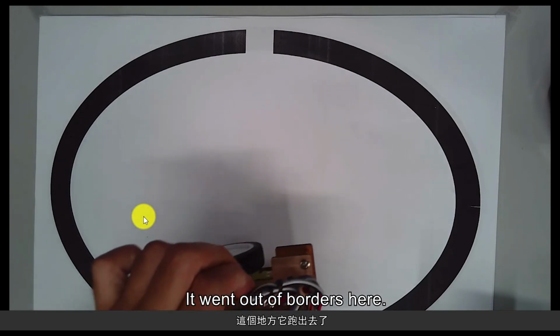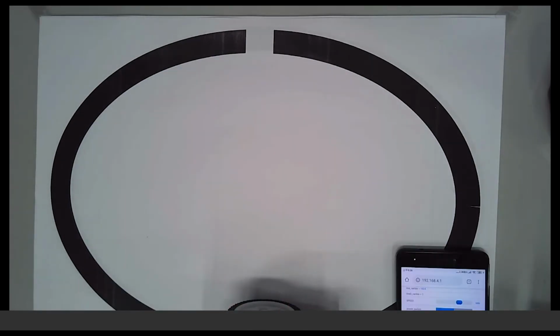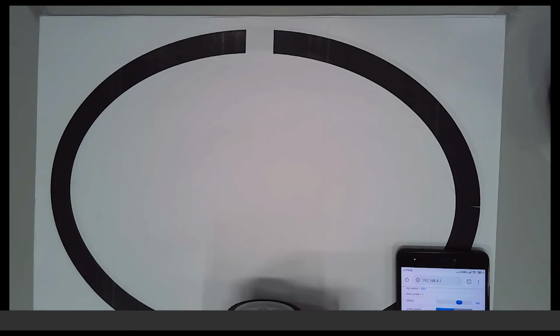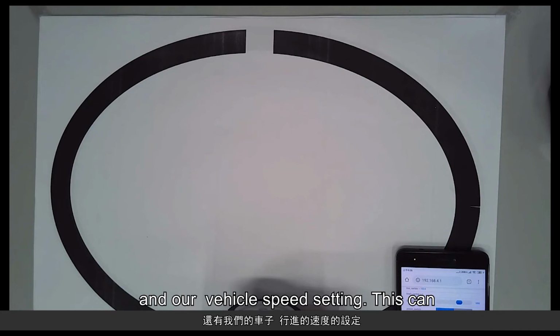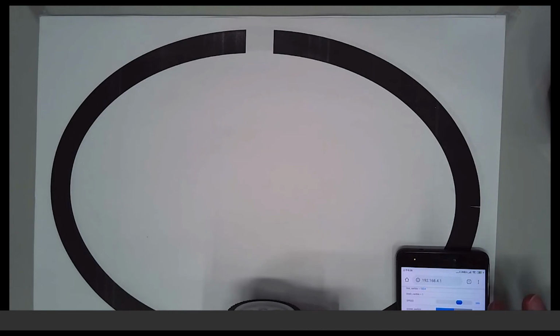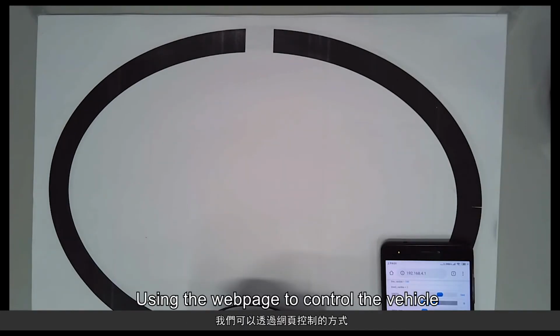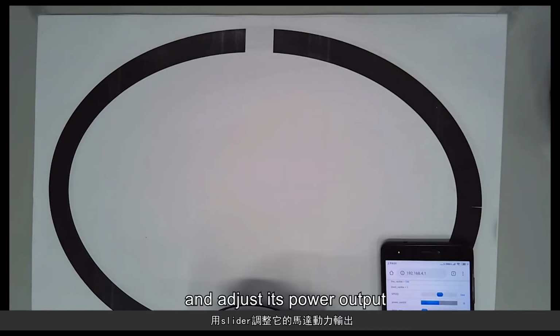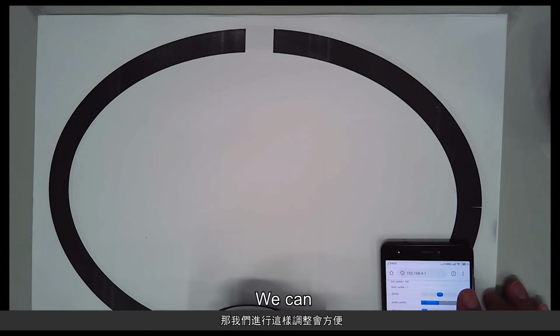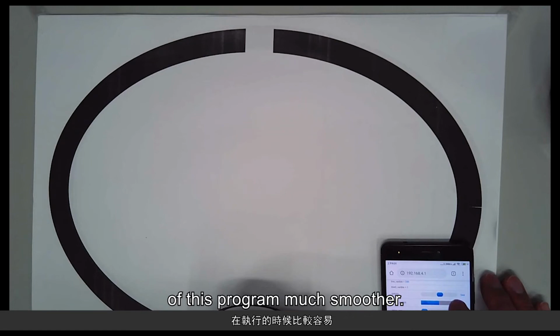It went out of borders here. When a vehicle tends to get out of bounds, we need to consider our delay time and our vehicle speed setting. This can be easily adjusted from our web page. Using the web page to control the vehicle and adjust its power output, and the delay time when it encounters a white line, we can make the execution of this program much smoother.